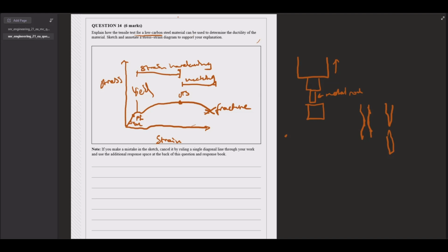So the other two marks for that first part is plastic deformation and fracture, which yes, you should be mentioning that. And providing an appropriately annotated stress strain diagram that shows the plastic region. That's my bad, I should have put that in. I didn't think that was particularly necessary for determining the ductility of the material, but you know, the upper yield point and the point of fracture.